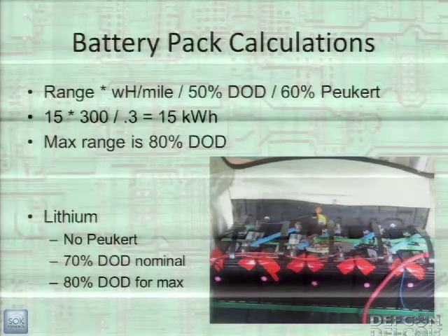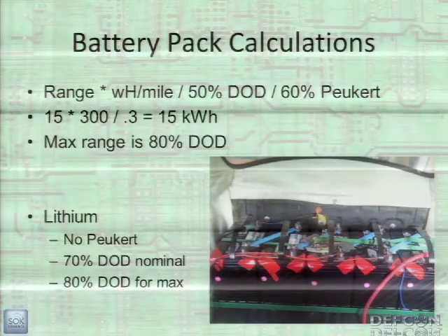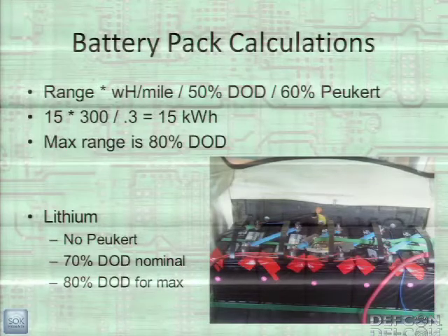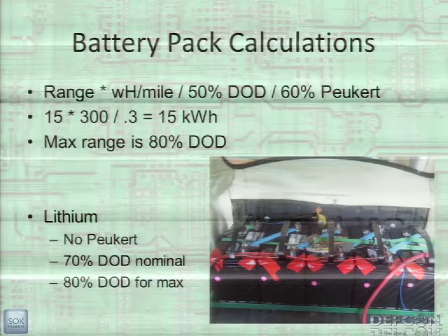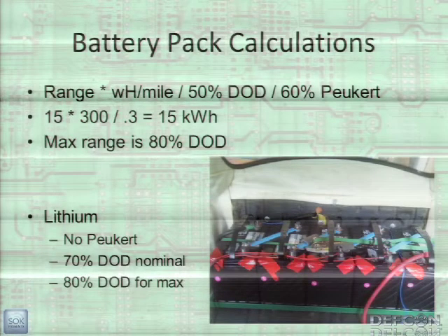So for lithium batteries, you don't have that Peukert effect, so you can use a lot more of the batteries. Also, you can discharge them down to 70 or 80% without hurting the batteries, so you can get a lot more out of them.